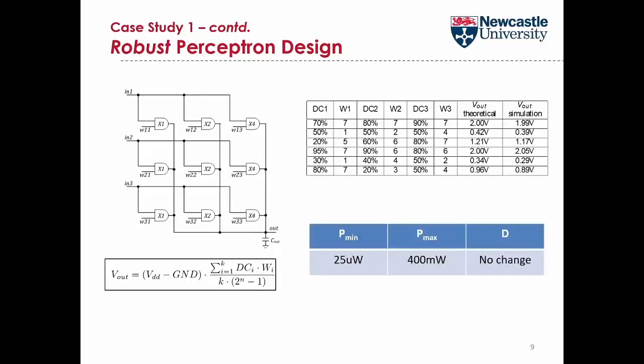And we also tried to stretch the, I think this number is probably wrong. It's in the range of 25 nanowatts you're looking at. Yeah. So you can see from the 25 nanowatt region all the way to 400 milliwatts, the device still works. So your power supply requirements and all the manic effort of designing a very complicated power supply can be greatly simplified if you possibly use the analog approach of this design.